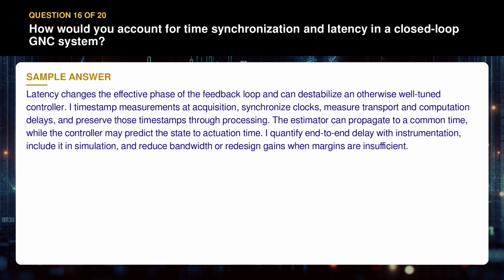Latency changes the effective phase of the feedback loop and can destabilize an otherwise well-tuned controller. I timestamp measurements at acquisition, synchronize clocks, measure transport and computation delays, and preserve those timestamps through processing.